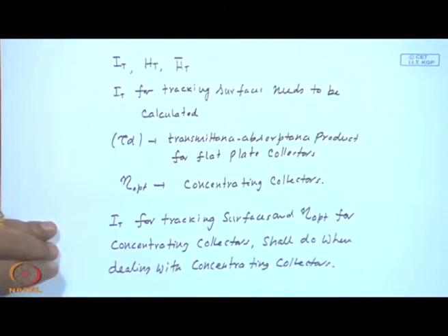concentrating collectors. So, for flat plate collectors, though we do not yet know how to design, we know that tau alpha should be high, and we know the method to estimate I_T in detail, whatever may be the time scale, and estimation of the overall loss coefficient U_L depends upon the knowledge of heat transfer, which you should have by now a fair amount of.